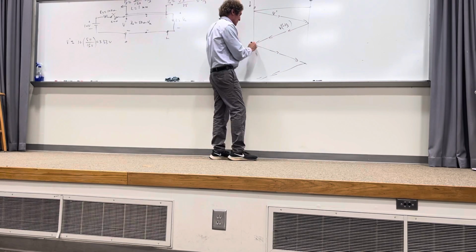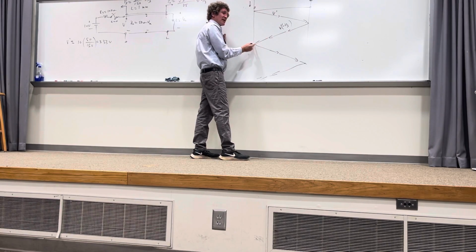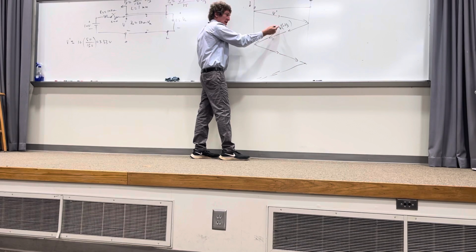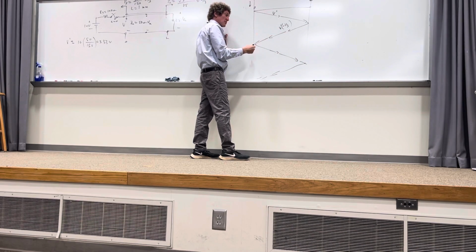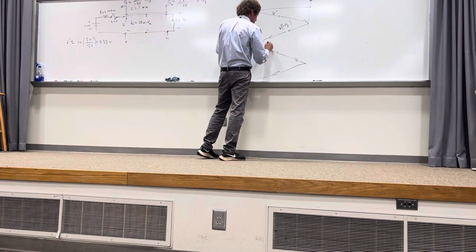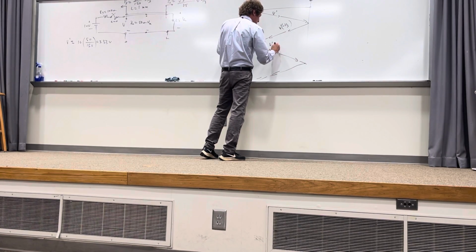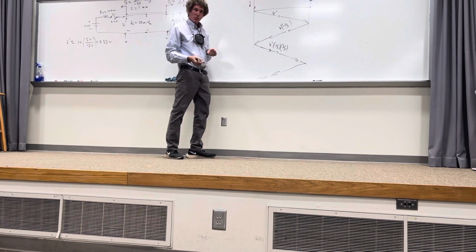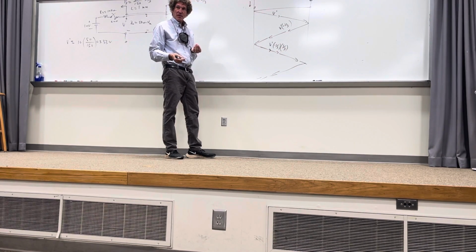It hits here. Now this wave hit here. Now I multiply this incoming wave by the reflection coefficient there, which is 1/3. So this wave coming back is going to be V prime times minus 1/3 times 1/3, or minus 1/9, right, times V prime.